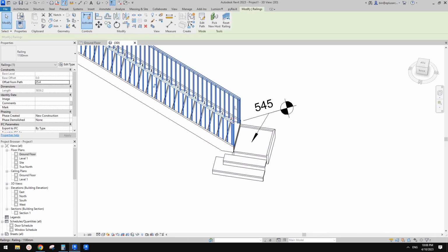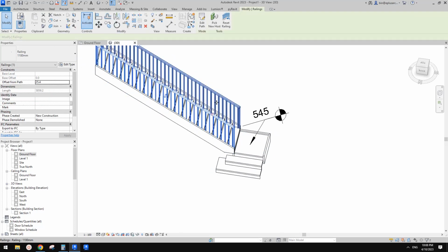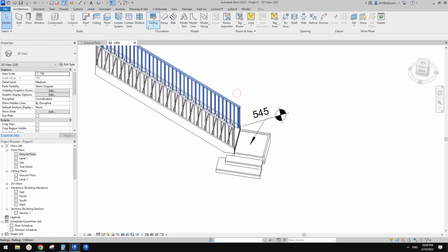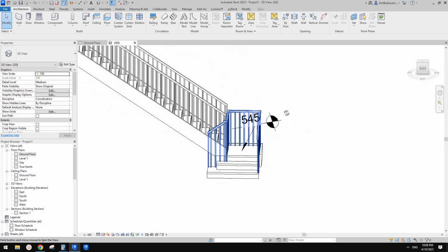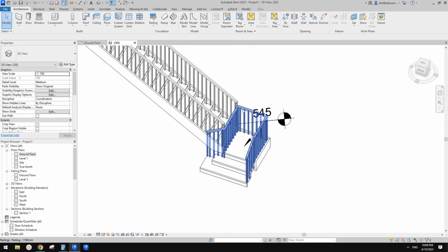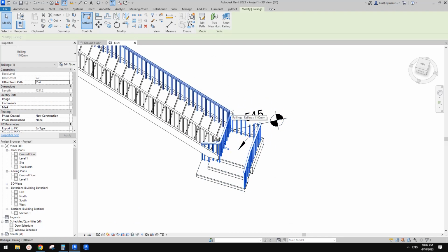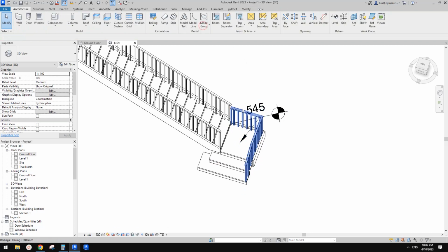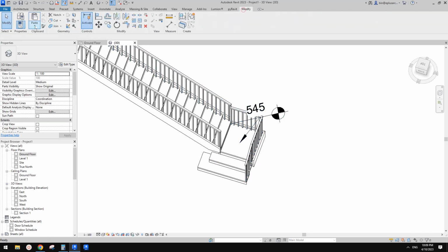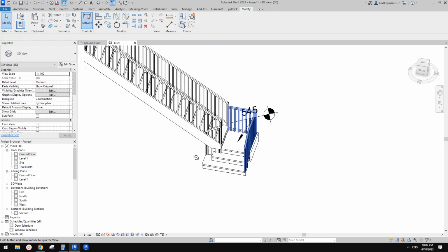So we have some issue, but because these are 2 different ones, once we create one, it only creates these 2 handrails. If I create another one for this, okay, we still have some issue here. But it looks like we can quite easily fix this. I'll just Control C, copy, edit path, delete this, and finish. So at least we have this one, and then I'll paste in the same place, edit path, delete this, finish this. Okay, so now we have everything, right?